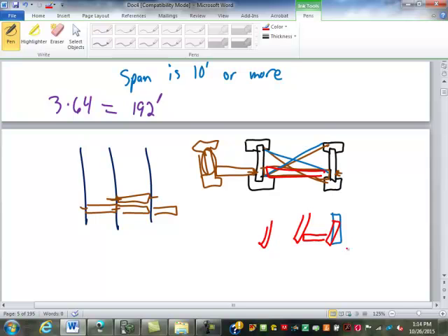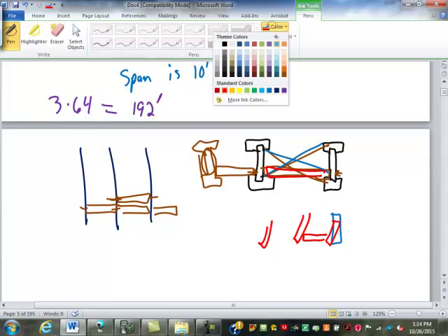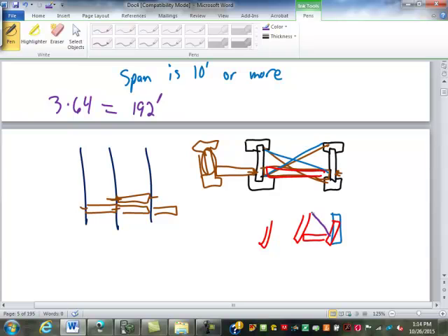But the X bracing moves it up to here. So now this cannot twist. It's not pushing against the side of this other joist, which can also move. It's pushing up against here, where that joist is attached to the floor. So it's almost impossible. The strong back is transferring that torsion, that twisting force, from one joist to the next until you reach a wall and it's totally stopped dead.